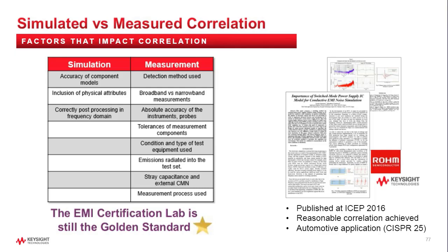Okay, thank you. The next one, by adjusting the rise and fall, can power losses in the switch improve? Absolutely. And that's another thing that, as I said earlier, run your EM extraction with the higher edge speeds, and that way the parasitics will all be incorporated for you to experiment with those different ranges, and you can plot the efficiency. It comes out in one of the answers we give as part of the test bench.